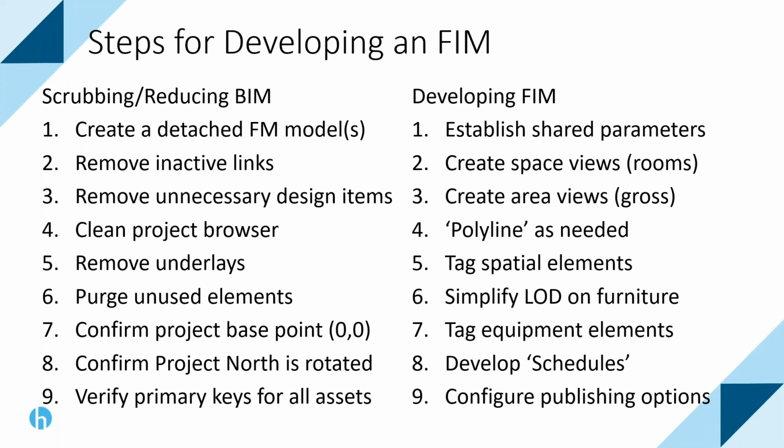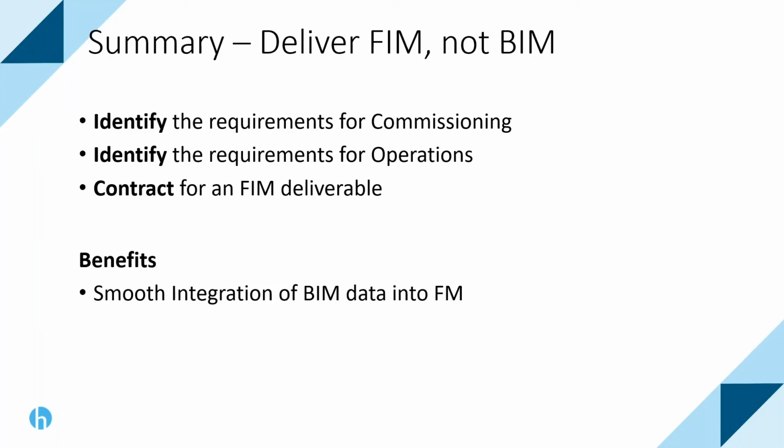for day-to-day operations. So just to very quickly summarize here, you want to identify your requirements for commissioning. That's what most people already do. You create a BIM execution plan for the design and construction BIM models. But not only that, for operations, you need to identify the requirements for FM. And for that, you're going to develop probably a facility information or a record model that you're going to use with Archibus. And in some cases, like I said, you may even need to have a separate contract for that, FIM or FM building deliverable.